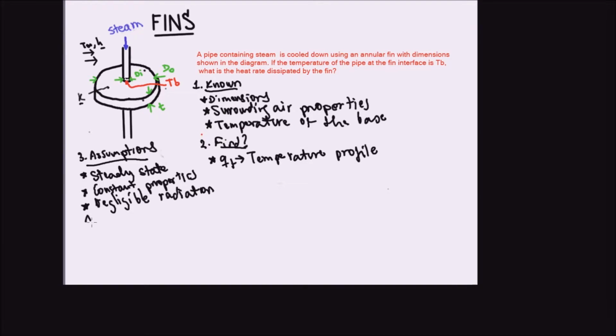And one of the most subtle assumptions that will help us simplify this problem is that the fin is very thin. So why is this such an important assumption? Well, let me first show you the axis of this system, or the possible directions in which the temperature could depend on, and then we'll see how having this thin fin assumption will help us simplify the problem greatly. Which will lead us to having a single dimension problem as opposed to 2 dimensions. So let's write that down. Thin.